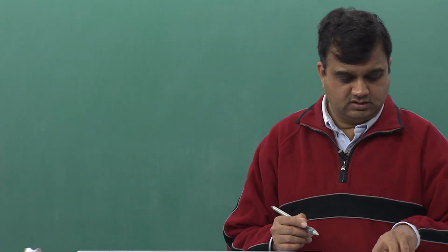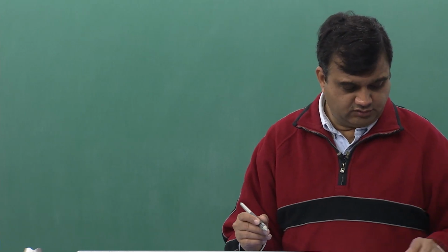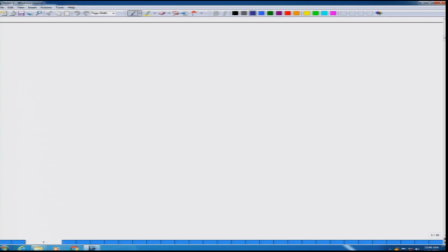So, for this lecture we will first write down the equations which we had developed in the last lecture, and the overall governing equation for 1D heat conduction with convective effects was this thing P. So, these two terms where beta appears, they are because of the effect of convection.